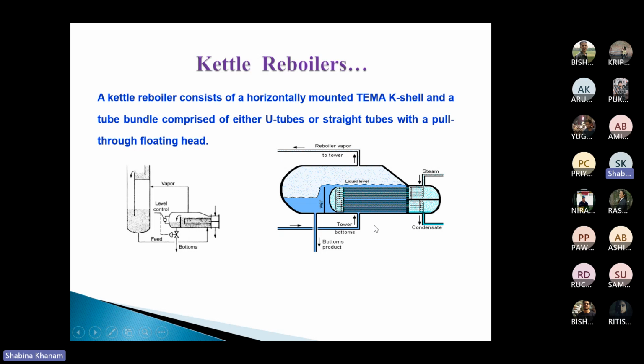That is mandatory. Boiling will occur only in the shell side, not in the tube side. So on the tube side we have the heating media, in most cases steam. So the tube side is steam, and the shell side holds the fluid we need to consider for vapor generation, or the bottom of the distillation column, whichever way you can understand.